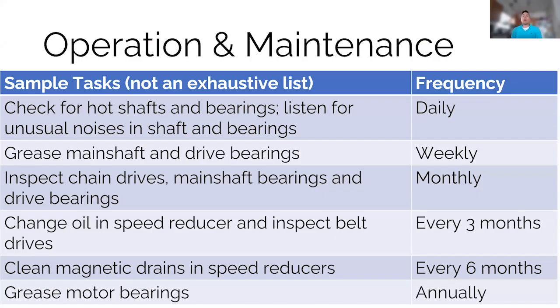So just a little bit of quick operation and maintenance. These are some of the tasks that you typically want to pay attention to for RBCs. You want to check for hot shafts and bearings to make sure that you're not going to get an RBC that breaks off. Also listen for unusual noises in shafts and bearings. You also want to make sure that you're maintaining grease on your drives and your shaft. You want to inspect the drives to make sure that the bearings and drive bearings are properly aligned.